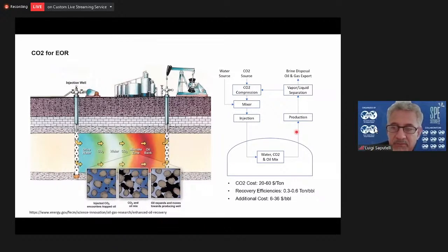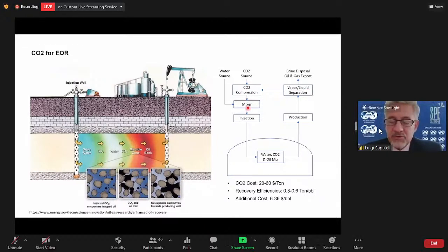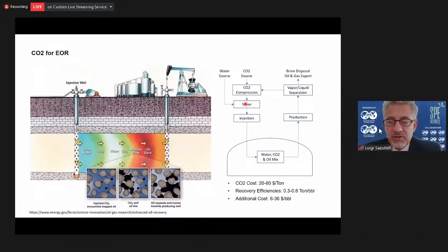With vapor liquid extraction, we will require more sophisticated metallurgy around the wellbores, because there will be a highly corrosive environment of water, oil, and oxygen coming into the oil. And perhaps we will also have H2S. We will need a good separation of the hydrocarbon gas, the CO2, and the liquids, oil and water. And by having hopefully an efficient process of CO2 compression, water mixing, and injection, this process can be highly sustainable.